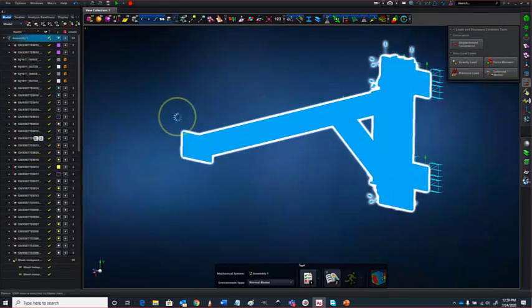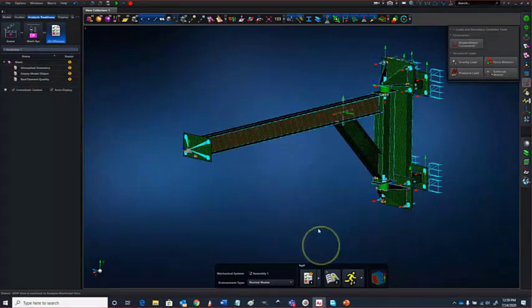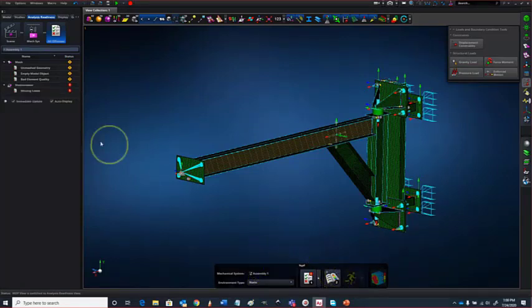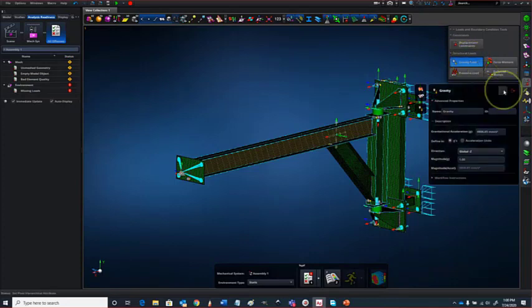So let's place this in the analysis scene. And it will reuse the computational parts from the previous analysis. I just need to switch to a static analysis. We can do the frequency response analysis or buckling analyses as well. And it's missing a load, which I thought I did create. Just add the gravity in the negative y direction.